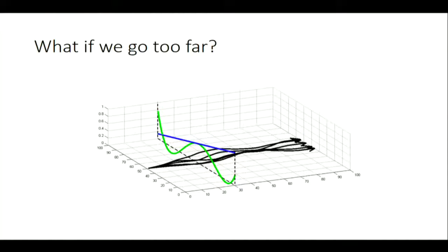So basically the problem is that our true dynamics are nonlinear. We're going to use this pretty silly linear fit to approximate the dynamics, which means that far away from our data it's going to be totally wrong. And if we feed those linear dynamics to our LQR procedure, it's going to give us a new controller that will maybe actually visit one of these regions where the dynamics are totally wrong. And when we actually run it on our real system, it might do something completely different.